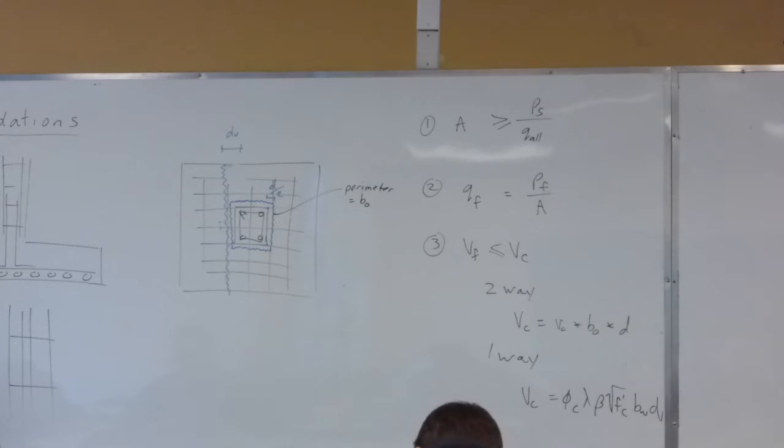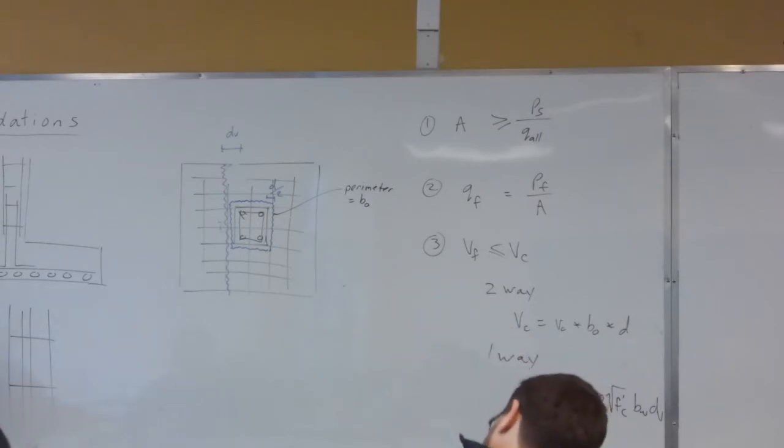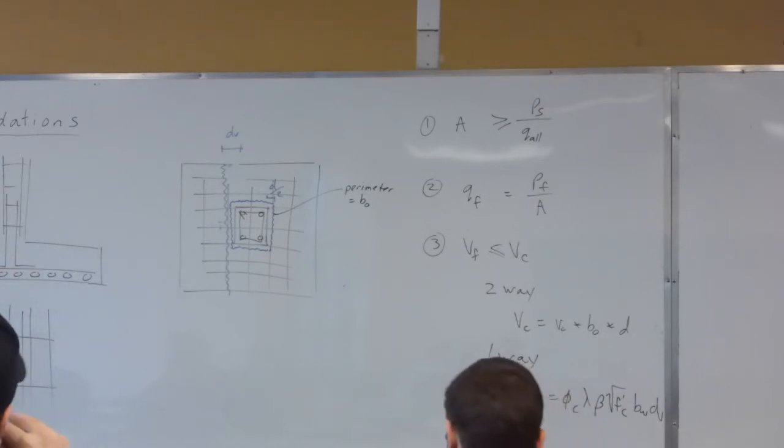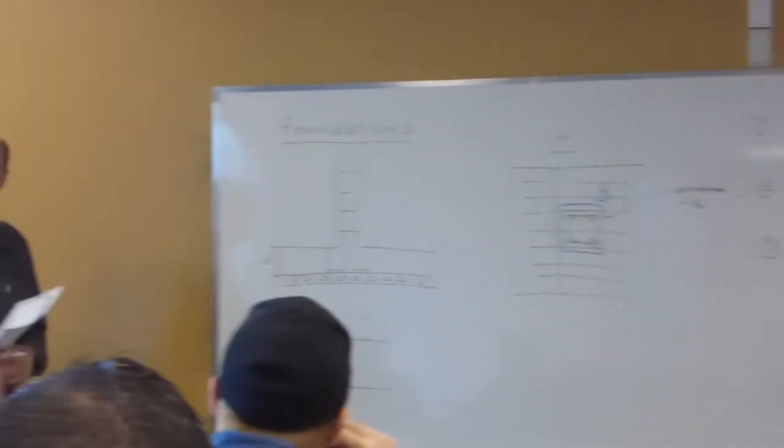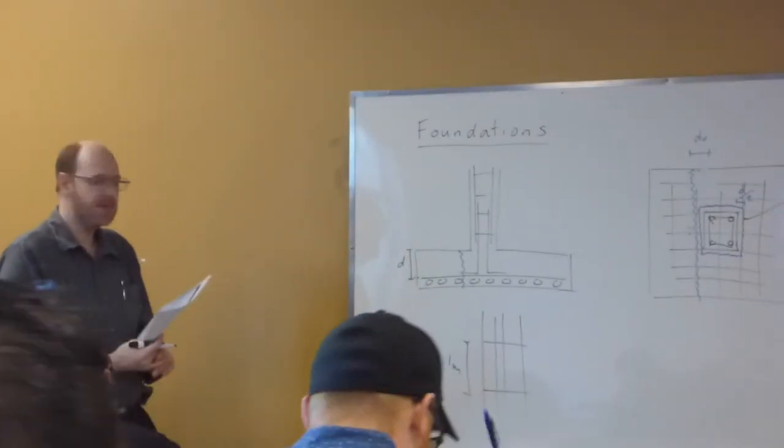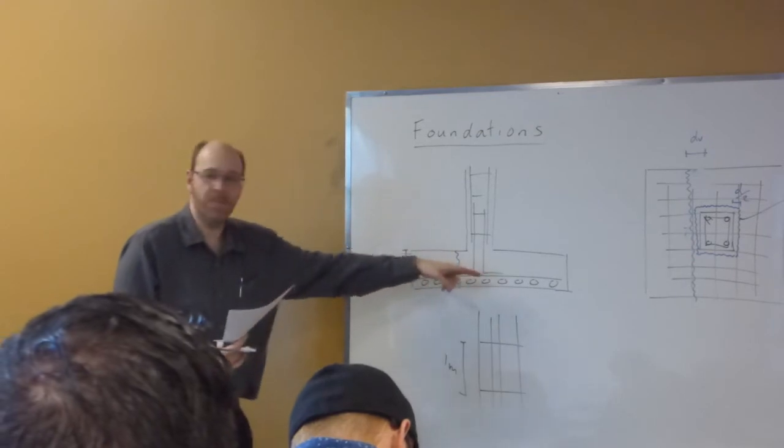You'll notice when we do our D calculation in an example, we've got two different rows in here. We're normally considering D to be the centroid of the row that we're actually analyzing. So when I've got two rows, I'm going to analyze based on the higher row, because that is the smaller value for D, so hence a conservative calculation. Some people actually take the average right in the middle here.